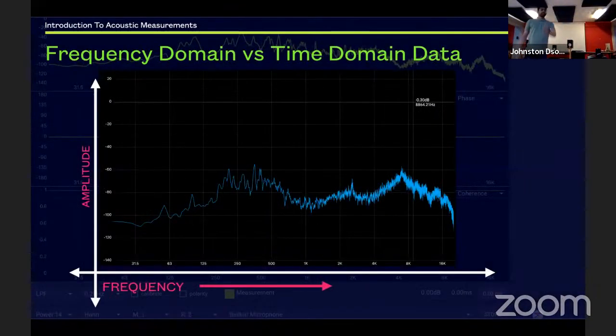So what you see in front of you is something known as a frequency domain signal. Now these two things you'll have to keep in mind because using FFTs we can do multiple types of measurements. We can get really complex with it, but we're just going to understand the very, very simple basics of it. So on the y-axis, we have amplitude. Amplitude is going to remain there always. That means what is the level of that particular signal, depending upon where you're measuring it. On the x-axis is frequency. That's why it's called a frequency domain signal. We are measuring frequency against amplitude.